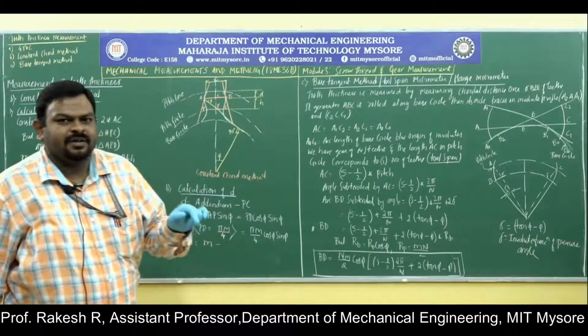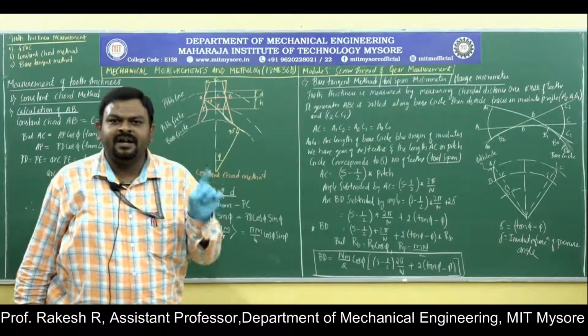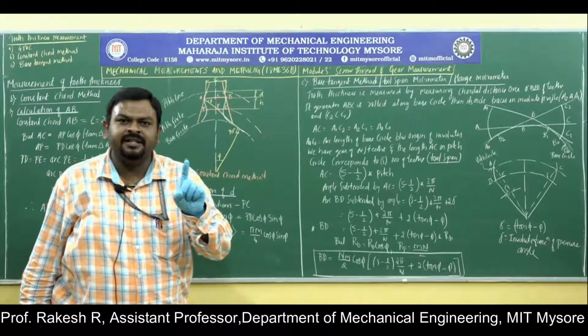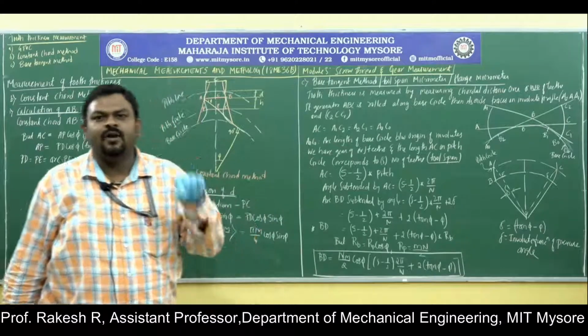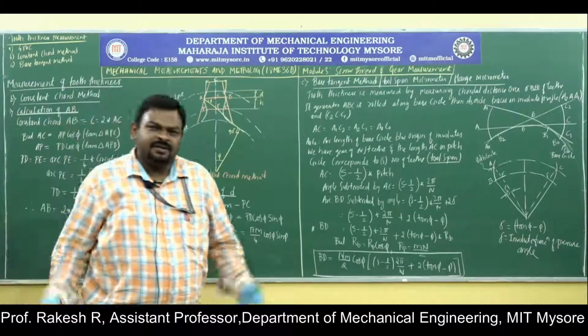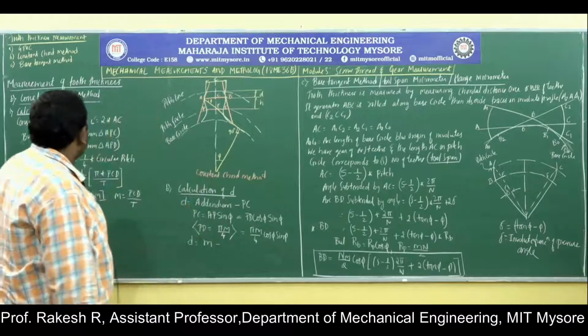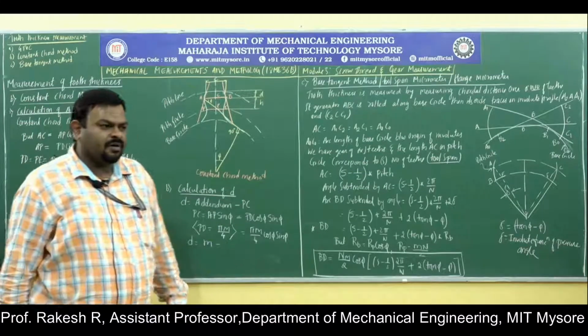If you measure using gear tooth vernier calipers, you can measure the width and depth of only one tooth at a time. In gear tooth vernier calipers, we need to know how many teeth there are. So the N by 2 relation is there. That is very important.